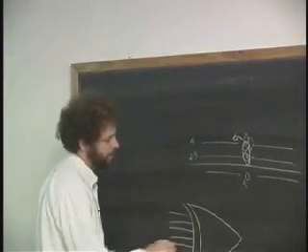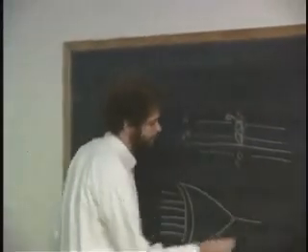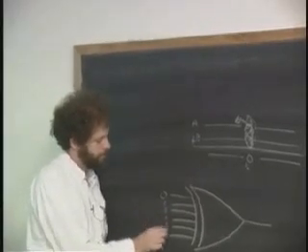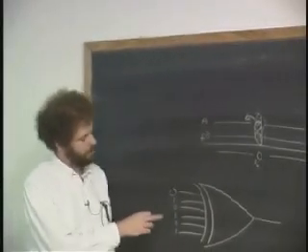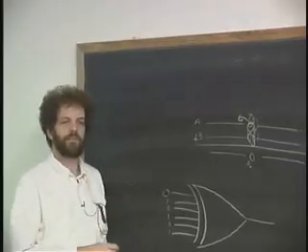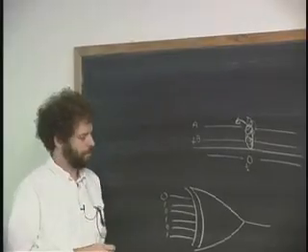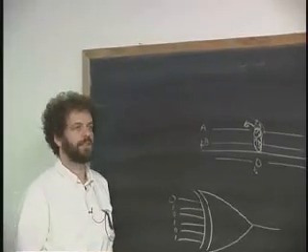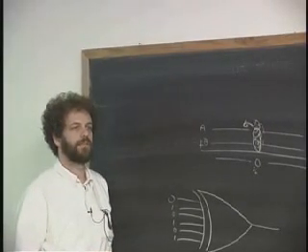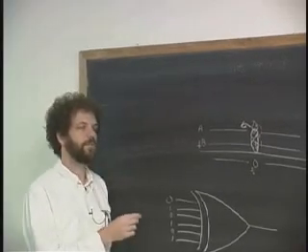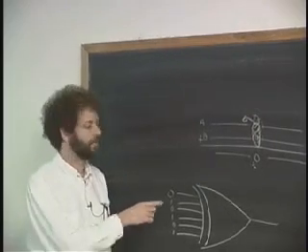And why is that? Because XOR has this incredible characteristic. If I have XOR of a whole bunch of bits, and here's an output, and let's say that I put in a bit string, right? 0, 1, 0, 1, 0, 1. What is the XOR of all those bits? Somebody said 0. Is it 0 or is it 1? What does XOR actually do? Gives you the odd or the even parity. That's absolutely right. It measures what's called the parity of the input here.